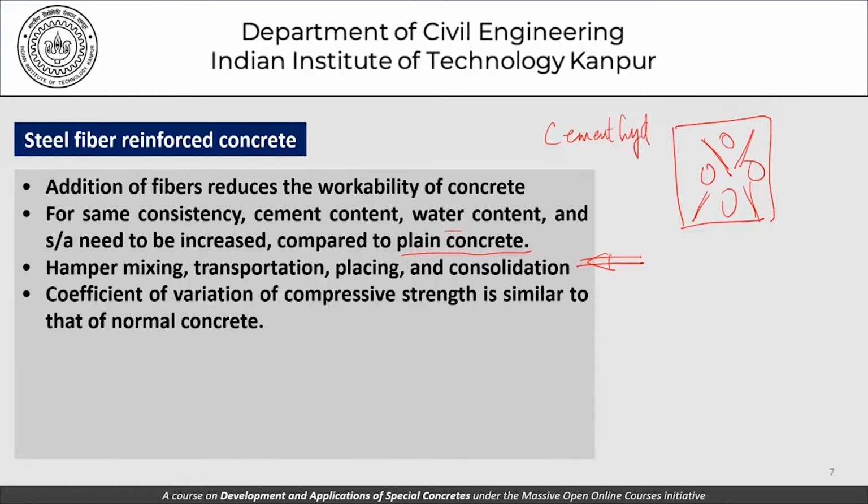And therefore, there is no reason to expect any change in the compressive strength or the variation in the compressive strength on account of fiber addition, except in a situation that we do not pay enough attention to the fiber addition issue in mixing, transportation, and placing, in which case the real culprit for observed changes in the compressive strength or its variation is our lack of attention to the mixing, transportation, placing issues rather than the fiber addition itself. So that's something which is very subtle and you must keep in mind all the time.